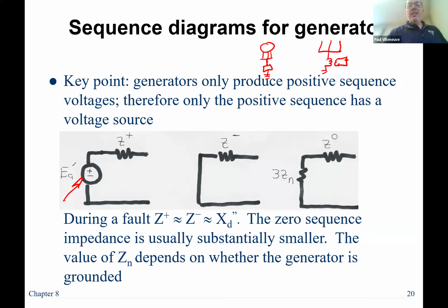So if this is, we'll call it a 12.47 kV to 240 volt transformer, then if this is a 10 ohm resistor, that 10 ohm resistor is going to have a much higher impedance on its high side because you're reflecting it to the high side, so the impedance is increased. So by far, what's very common for generator protection and grounding is you have a step-up transformer, and then you have just a baby resistor, just a regular old resistor that can handle 240 volts. So not one of those quarter-watt resistors that you find in the lab, right? You're going to have some power and some voltage across it, but it doesn't have a lot of power. But the impedance gets stepped up quite a bit because of the transformer.